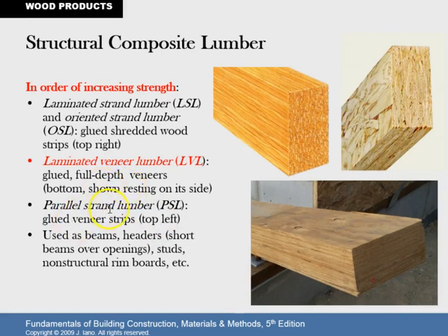And then parallel strand lumber, glued veneer strips, top left, so that's here. I don't believe I've ever actually seen this in person installed. In general, these pieces are used for beams, headers, which are short beams over openings, studs, and I can't say that I've ever seen them installed as studs either. Perhaps a post or a small column, yes, and non-structural rim boards. So I've seen it in all applications except studs, I would say.